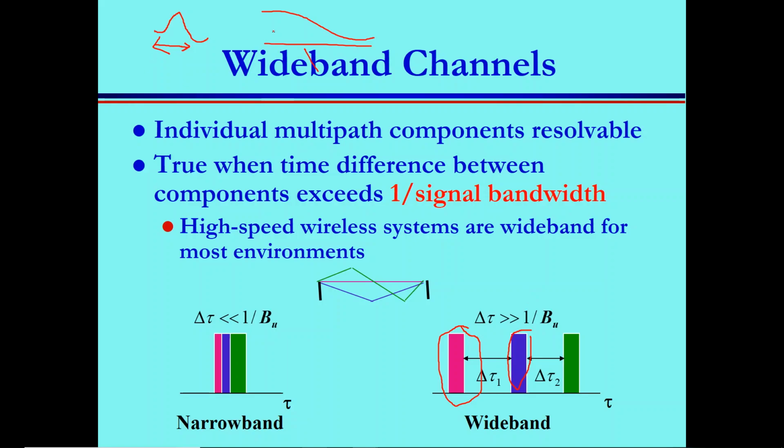Why? Because you have your symbols here back to back. And as you know from signals and systems, when you send your signal over a channel that has this delay spread, your signal gets convolved with the channel. Everybody remembers signals and systems, because it's very important for you to understand the effect of delay spread.